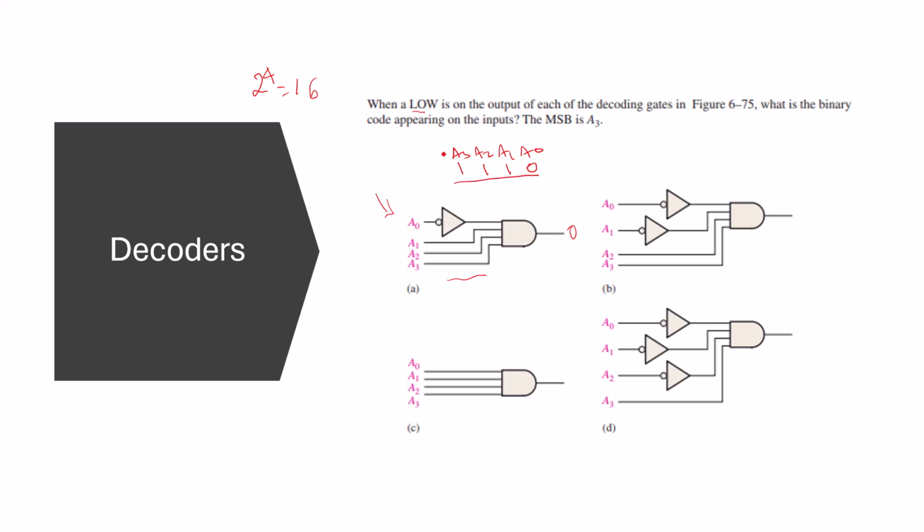So the question is asking, what is the exception? What is the exception, that it is like this circuit excludes this kind of combination? So what does this mean? It means if I put them all 0, will it do? Let's see. If I put them on 0, then this will be 1, and this is 0 0 0, and because this is an AND operation, then there will be low.